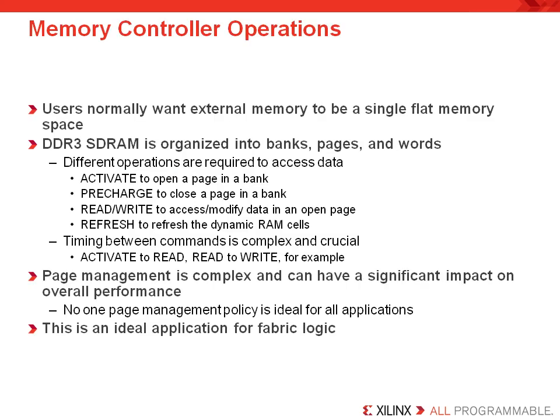So as you know, memory controllers store data in banks, pages, and words. And of course, depending upon the type of operation that you're using, this is going to have different requirements. That's because the DDR3 SDRAM is going to organize that data, and it requires different operations to access the data: activating to open a page in a bank, doing a pre-charge to close a page in a bank, doing read-write transactions to access and modify data, and of course refreshing the dynamic RAM cells.